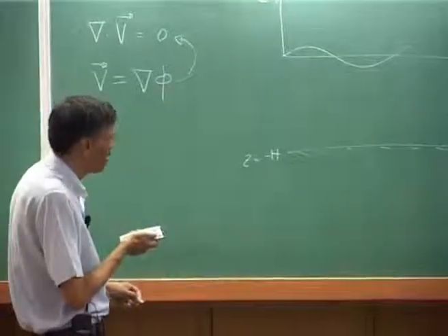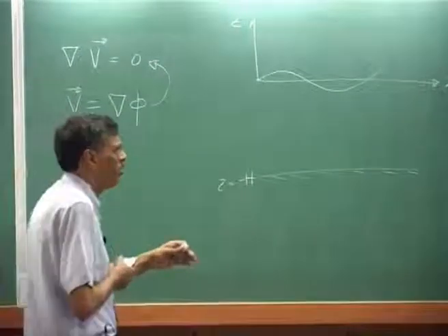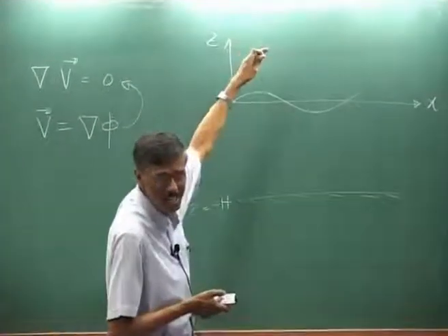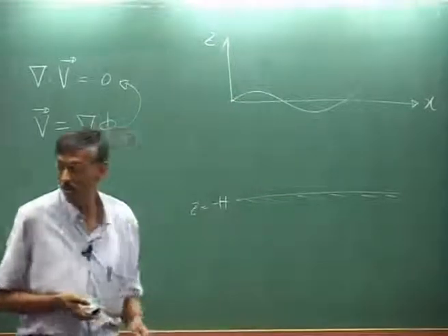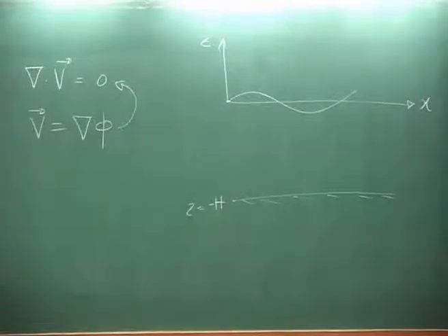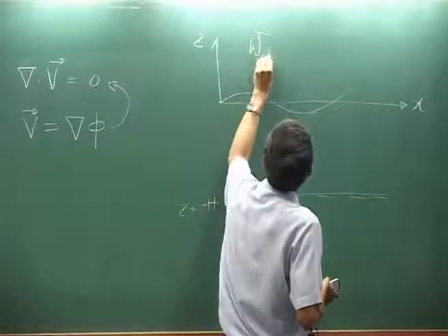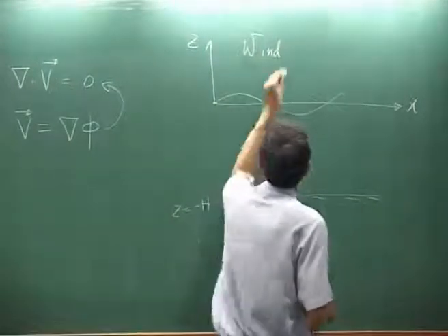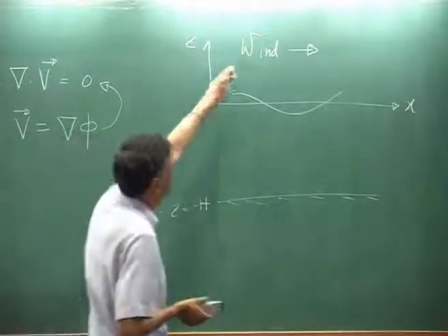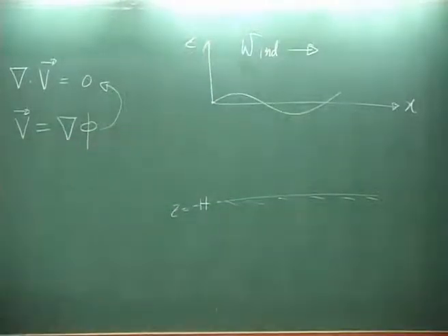While at the free surface, at the mean position, we will just simply say the fluid would not leave the surface. It would not go out and form a bubble here floating in the air. That of course is possible and feasible. People do it in multiphase flows, but we will not talk about it, because here of course ostensibly we will have wind here blowing, and we do not worry about its contribution to the dynamics of this wave in the analysis that we are doing.